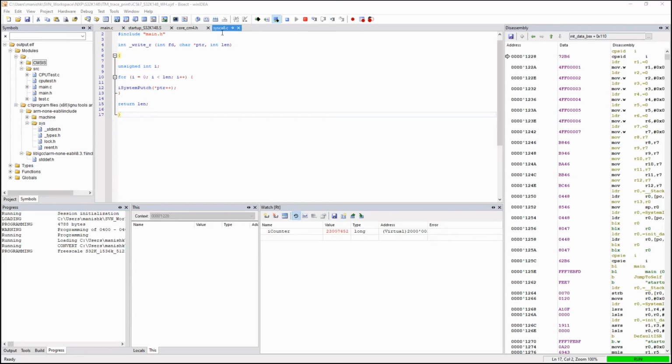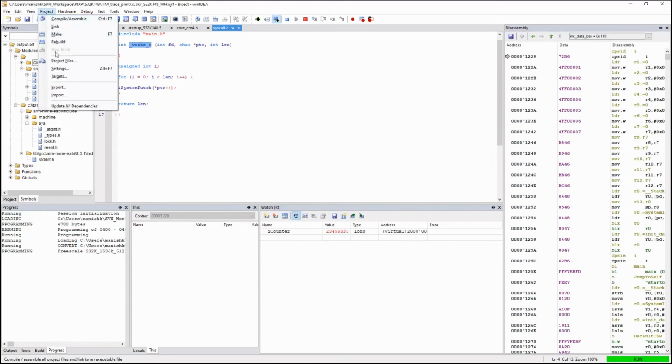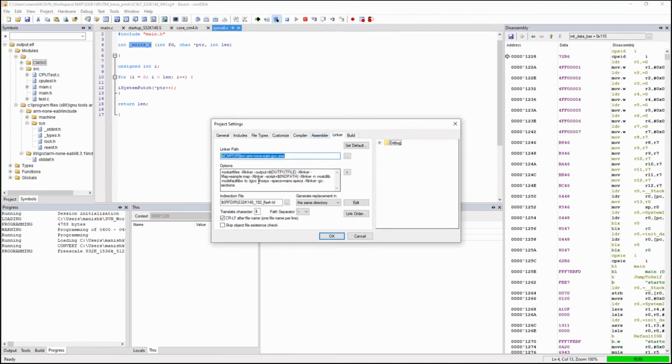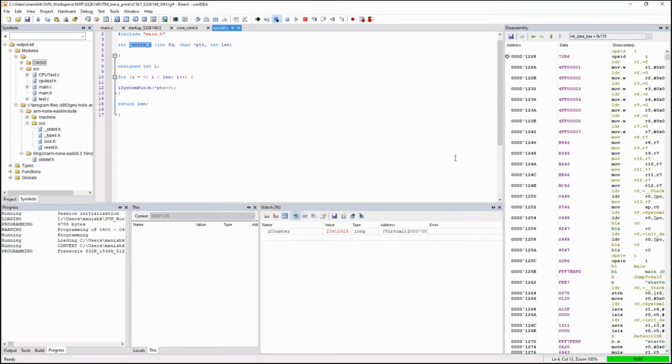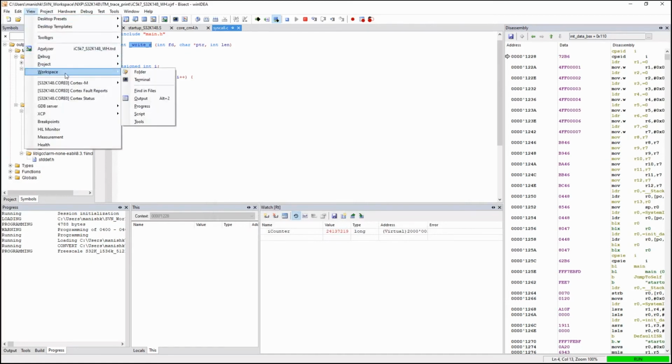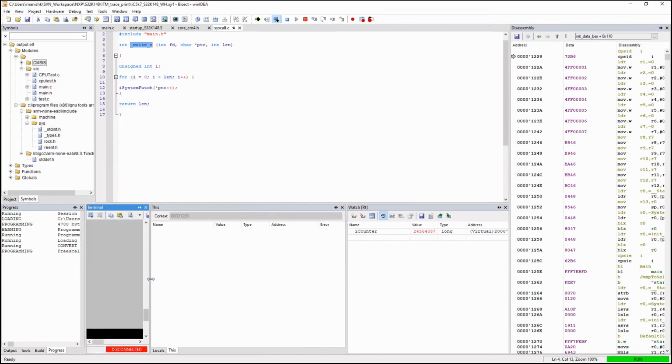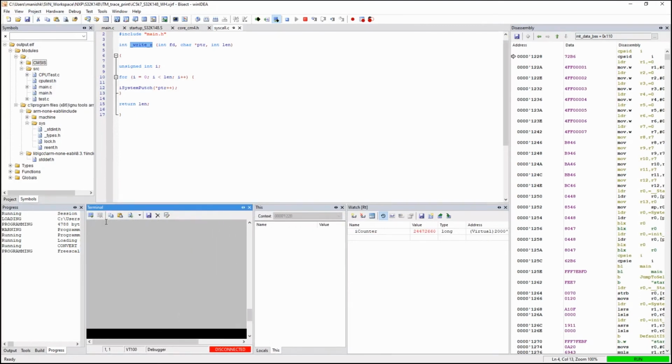So this is my syscall.c file. Basically, the syscall.c file implements the low-level functions. There are a few specific linker settings which you need to add. So you must add this. Now let's open the winIDEA terminal. There are a few settings which you need to do.